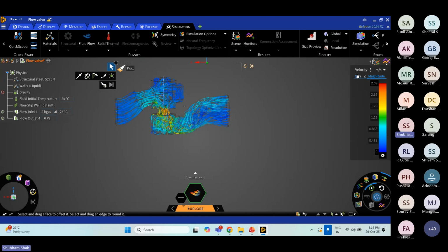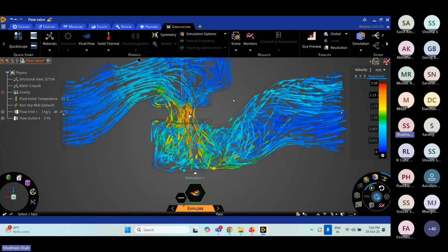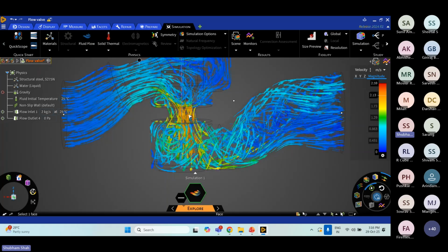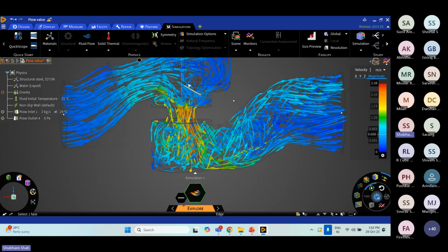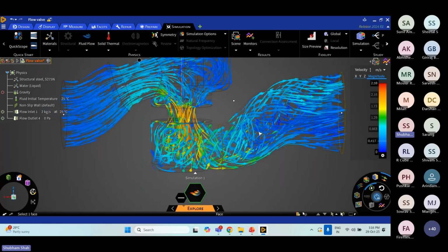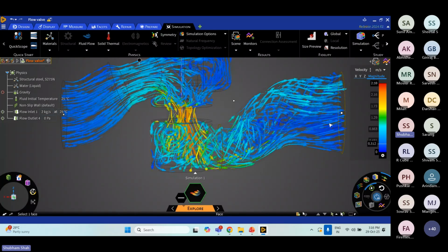And on the right hand side, there is a legend. You can see the minimum and the maximum values of the contours. So basically velocity is there. So let's say I am pointing my cursor over here. If you see on the right hand side in the legend, that horizontal line is indicating the value, so whatever the maximum value is will be replicated on the right hand side. So if I am taking this over here, the value of velocity is 0.312.